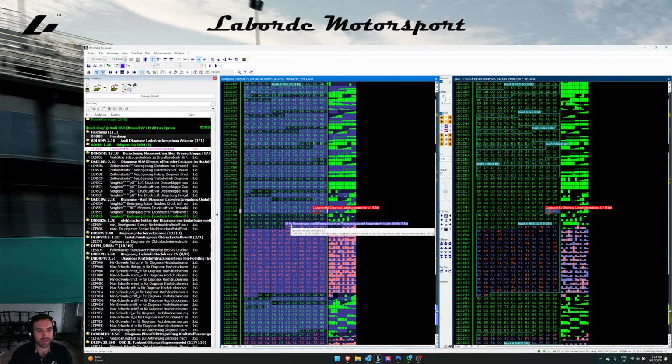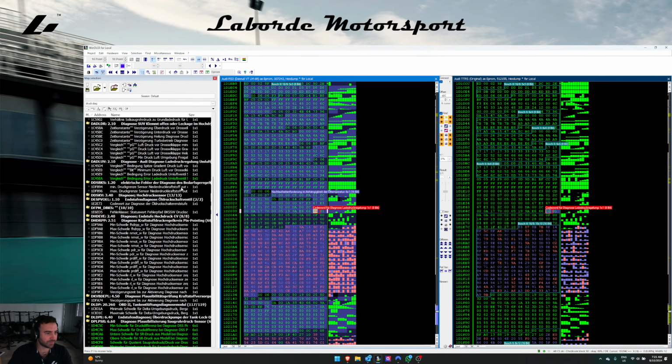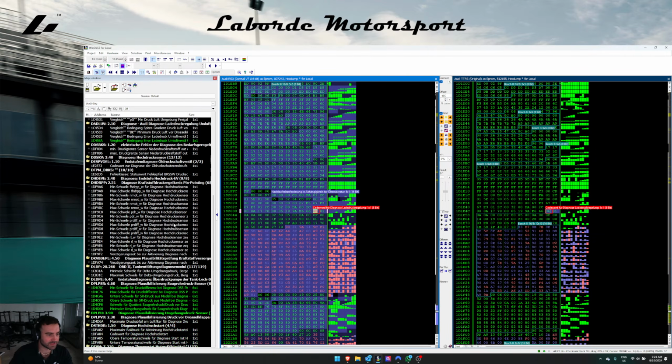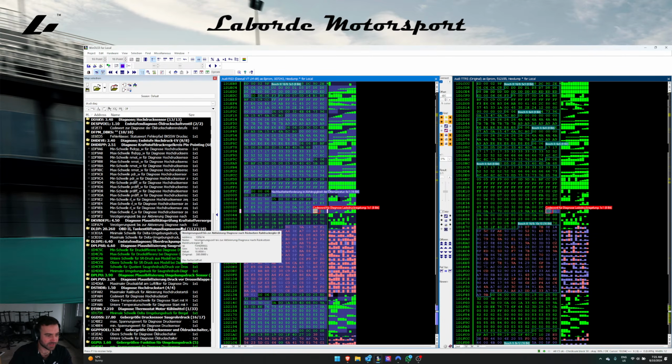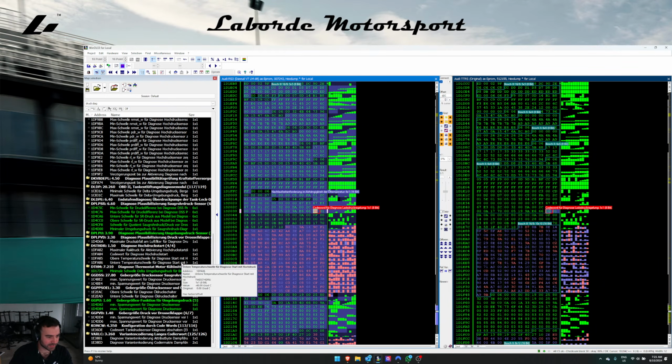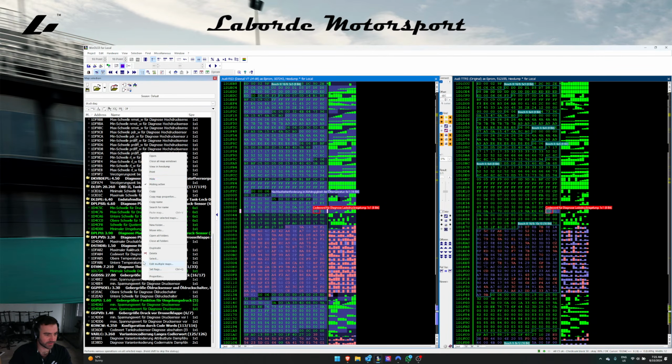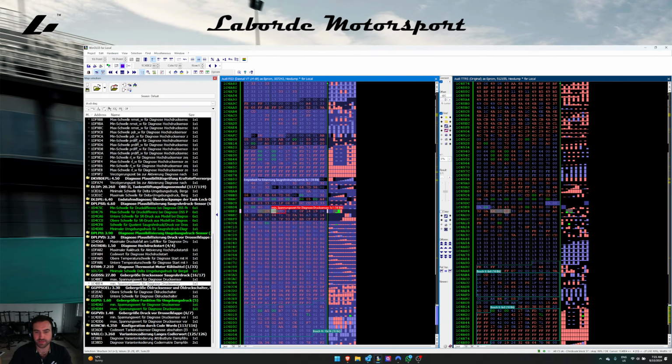That's 255 kPa or 1.55 bar of boost positive pressure. So that's why any boost above that for this particular car, you need to run it in an open loop because you'll get throttle closure, and coupled with that, you need to disable the regulation of the boost pressure. I don't recommend disabling these sorts of things on your stage 1, stage 2 cars, but when it comes to other vehicles like this, which are a very unique setup and require this sort of programming, then it's all good to go ahead and do those sorts of things.